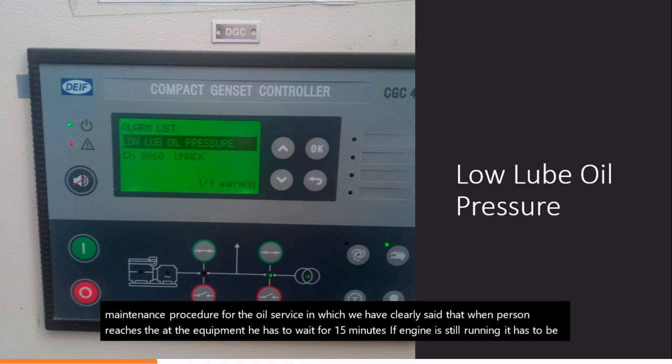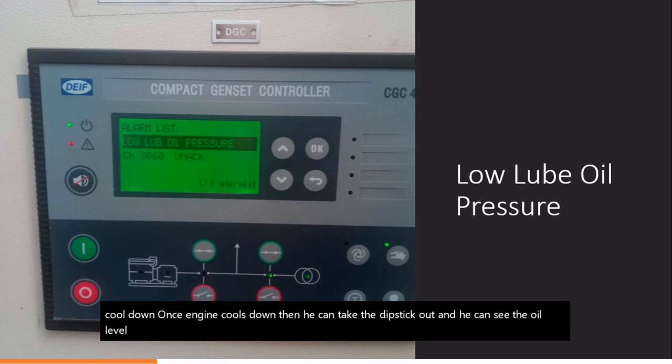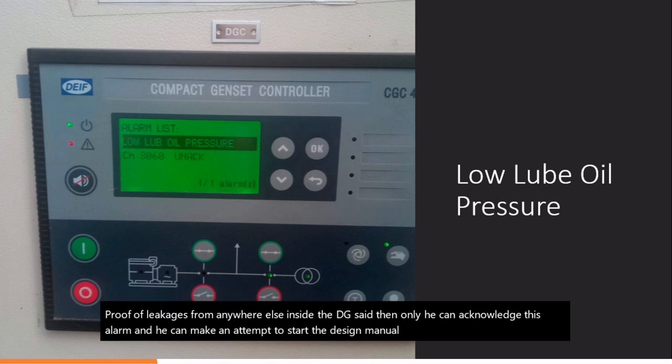Once the engine cools down, he can take the dipstick out and see the oil level inside the oil tank. If the oil level is sufficient, and there is no proof of leakages from anywhere else inside the DG set, only then can he acknowledge this alarm and attempt to start the DG in manual mode, and he will validate exactly what lube oil pressure is coming.